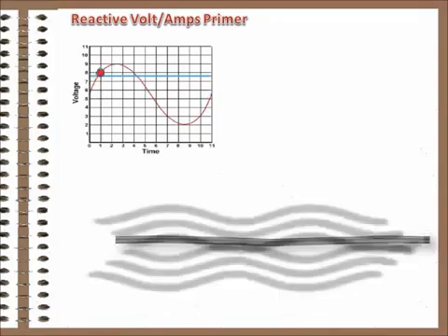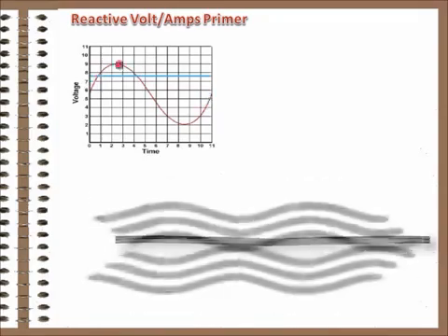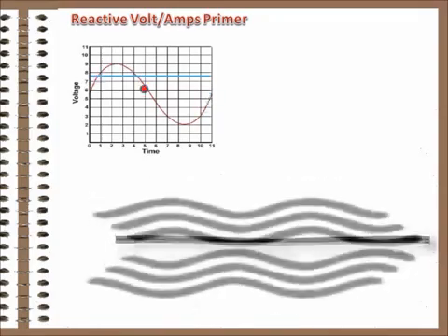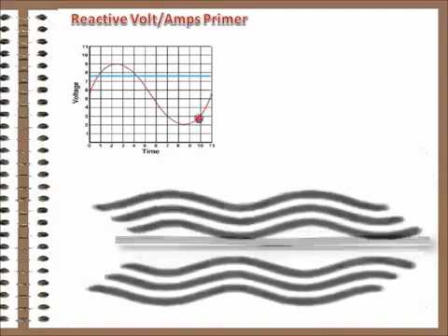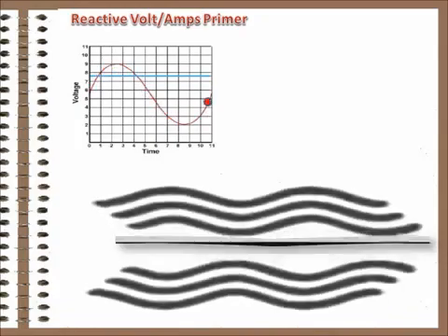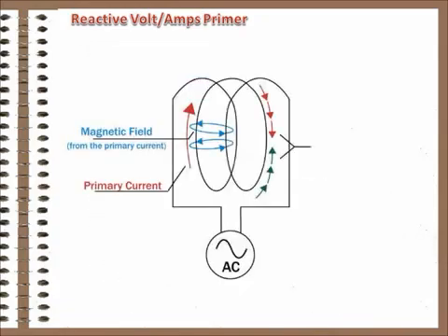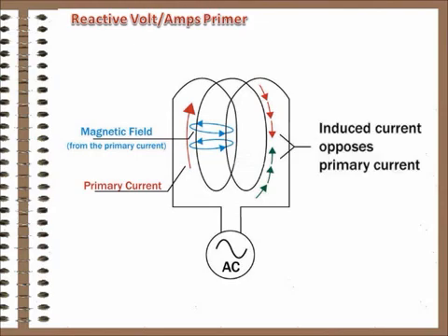So now, 60 times a second, energy is taken from the circuit to make the field, and then added back in when the AC current changes direction and the field collapses. But it's not an even exchange. The energy is added back in all right, but it's added back in right at the time the current is trying to change direction, and it delays the change.